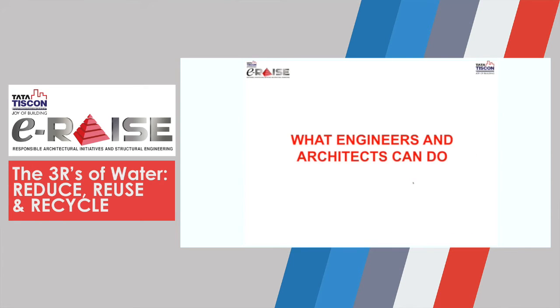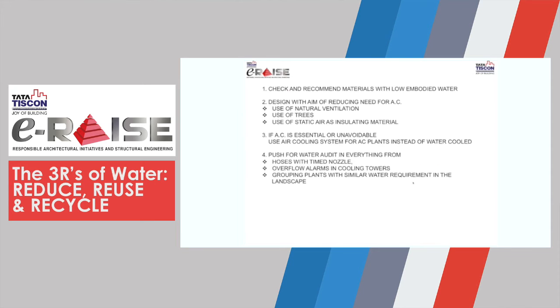What can engineers and architects do? All this time we were talking about what everybody can do. Now let us elaborate on what engineers and architects can do. Check and recommend materials with low embodied water. Second, design with the aim of reducing the need for AC by the use of natural ventilation, use of trees, use of static air as insulating material. If air conditioning is essential or unavoidable, for example, in hospitals, in hotels, air cooling systems can be used instead of water-cooled systems for AC plants.